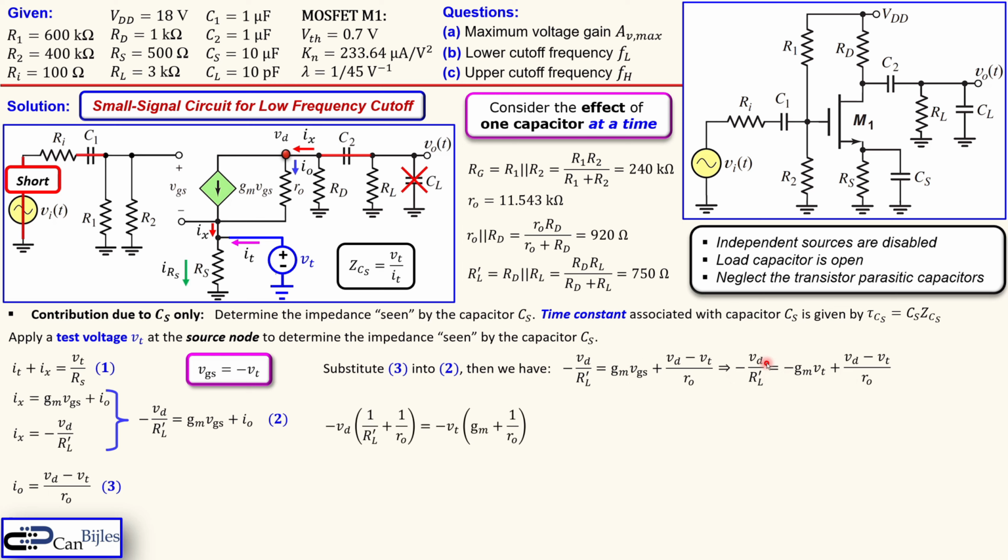Okay, I will now bring all the VD and all the VT terms together. So I have here VD over RO. I will place it to the left side. And of course everything is minus, so I will put the minus VD out. And also the VT terms, so minus GM VT. And also the minus RO, I will also put it in parentheses here and take the minus out. Now you see the expression of VD in terms of the other parameters we can use.